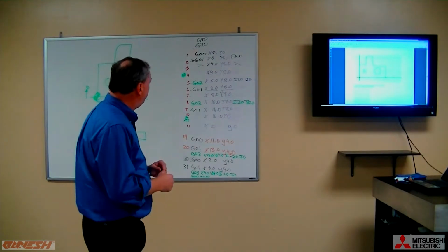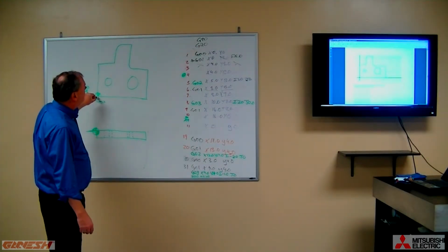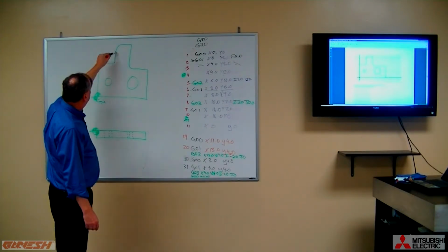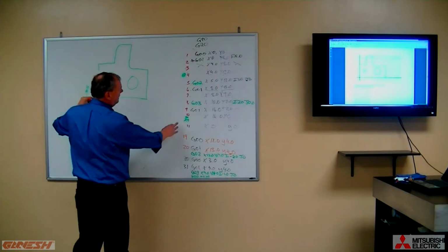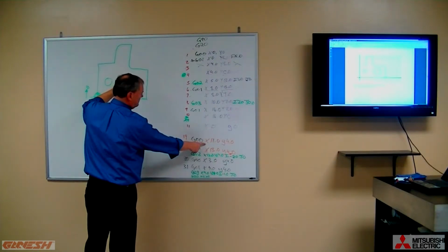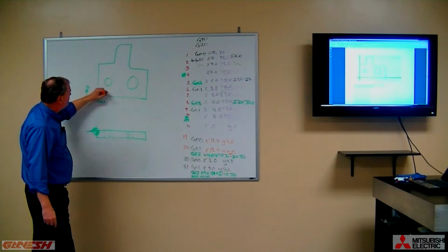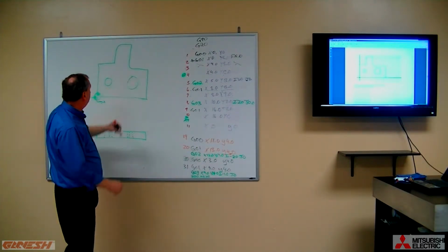So in other words, can you imagine what would be happening if we started this part program and we actually had a cutter down in material, cutting this part, and then we get over to this point right here where we want to jump to this circle? We make a rapid move. Mind you, the cutter is still in the material and it's going to rapid travel right through the thickness of our part.